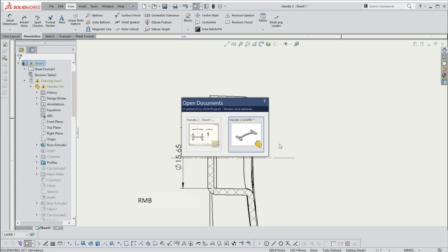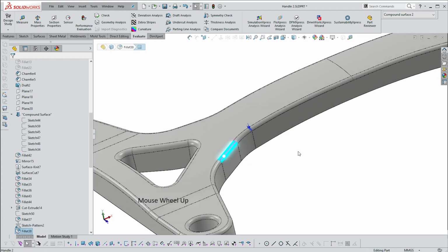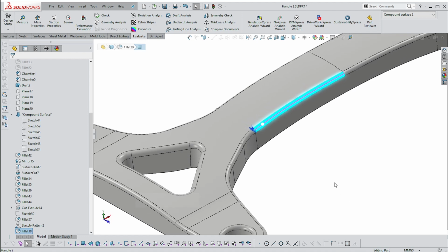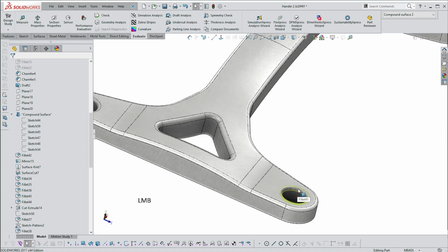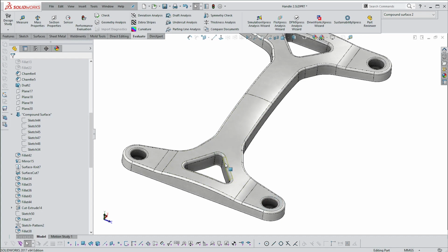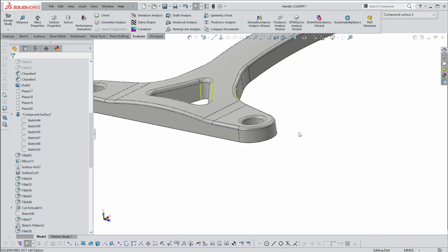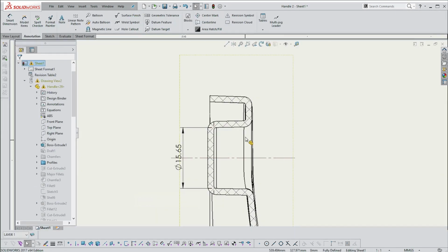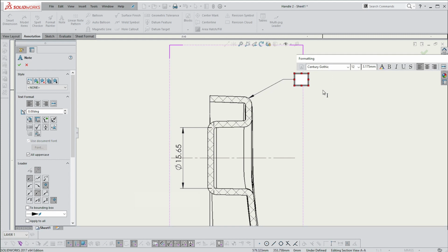I'm just going to hop across to my model. It's much easier. Here I can select the fillet. It'll tell me at the bottom. Seems not to, but there we go. There's that dimension. That's 2, and this one here is also 2 as far as I know. There we go. It says radius 2, and this one here I think is a bit bigger in my case. So that's 2.8. Right, with that knowledge in mind, we can dimension this by just using the note. So I'm going to wait till that little leader appears and then type in R. It's a radius, not a diameter.